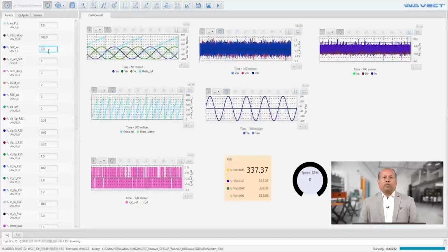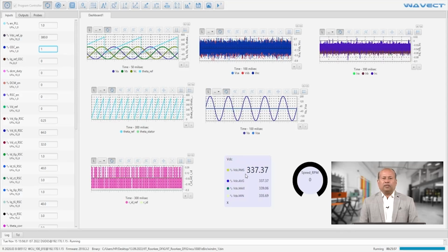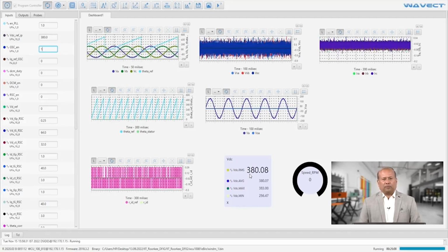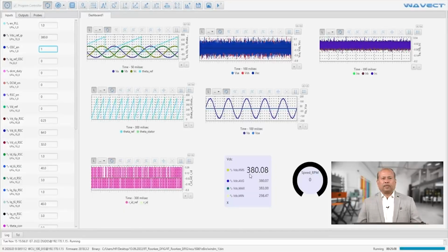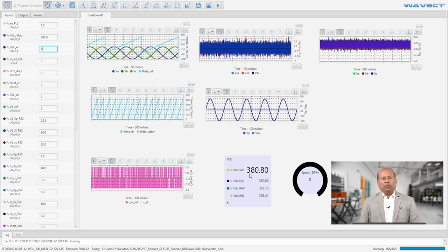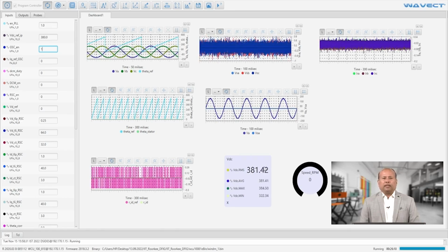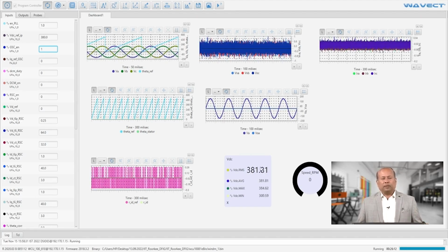Once the DC link is charged, we enable the GSC control to maintain the desired DC link voltage, which is set to say 30 volt greater than the DC link voltage, that is close to 380 volts. We see that the GSC tracked the DC reference voltage and the measured DC link voltage is read as 385 volts.